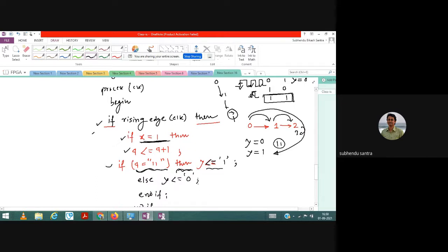And let us say you put a reset button or something like that, so from the last state it can go once again to the 0 state and then repeat. So this thing can be done. Intentionally we can do different types of lighting sequence arrangements, traffic light signaling. So we will not directly complete the count, rather we'll keep on looping the count, but when the count is completed, the output is equal to 1, otherwise it is 0.